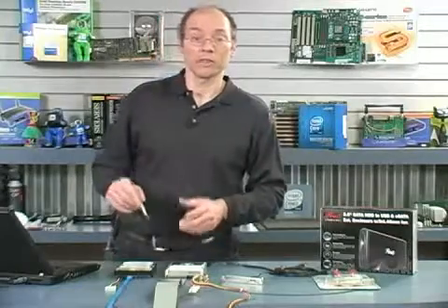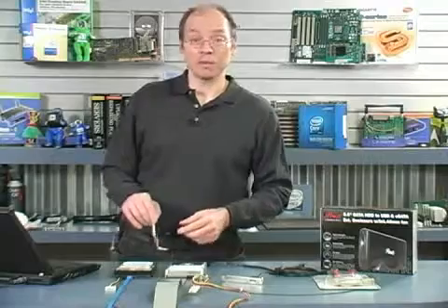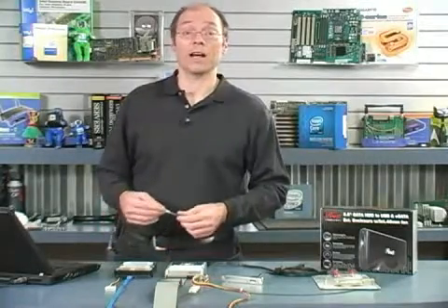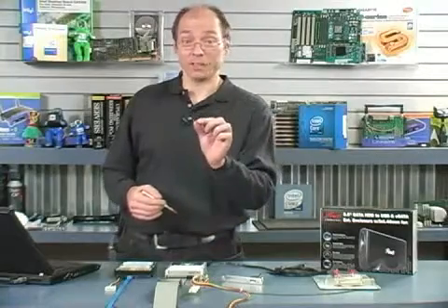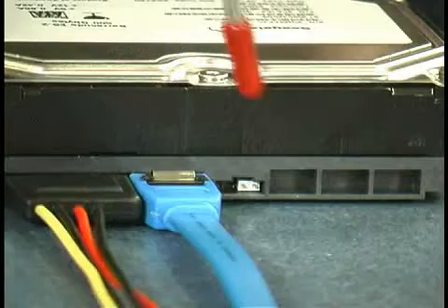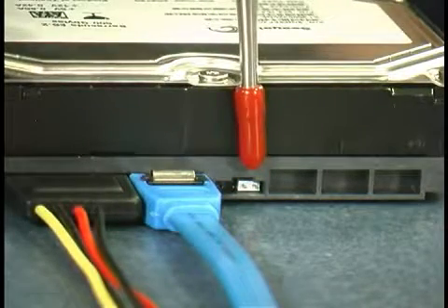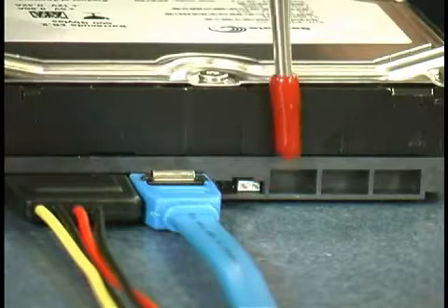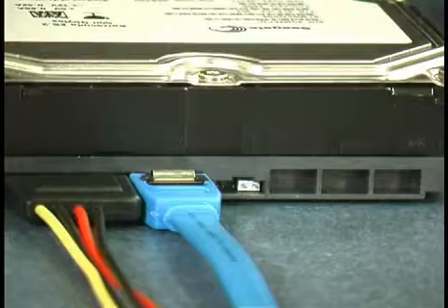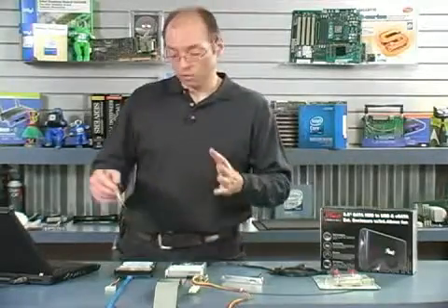And guess what? Virtually all the drives I've seen lately ship with that jumper enabled. So I just bought 6, in fact, of these serial ATA drives. Every single one of them had the limiting jumper in place to knock it down to half the speed. That jumper is, by the way, positioned right here. It's a little tiny gray jumper on this drive. I need to get a tweezers out and take that jumper out, because the motherboard I'm going to be connecting this to will support the 3 gigabit per second rate, and why would I want the drive running at half speed?